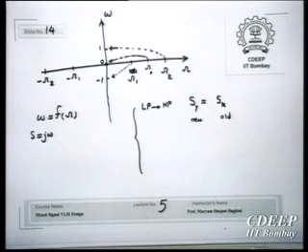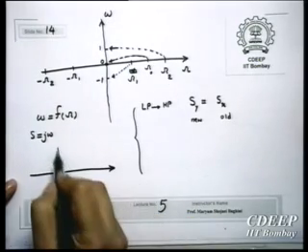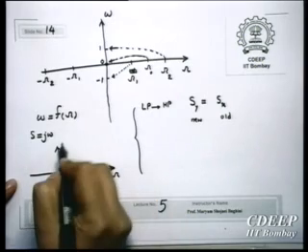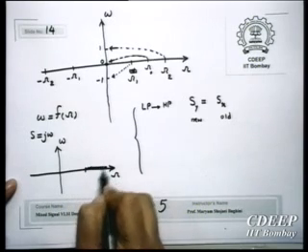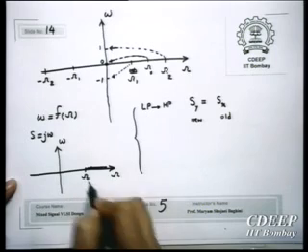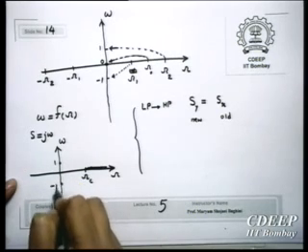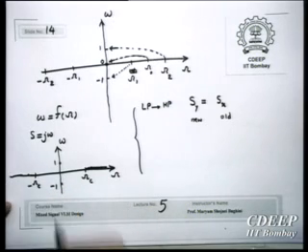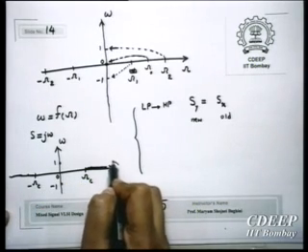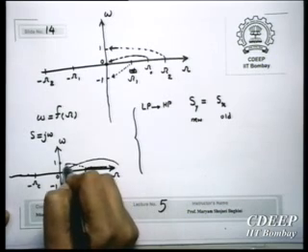Starting from this and then going to the others, this is easier. This goes to infinity, so I will have only one corner frequency, omega c, 1, minus 1, and here minus omega c, infinity. I want to transfer my infinity to 0, and omega c, for example, will be transferred to 1.